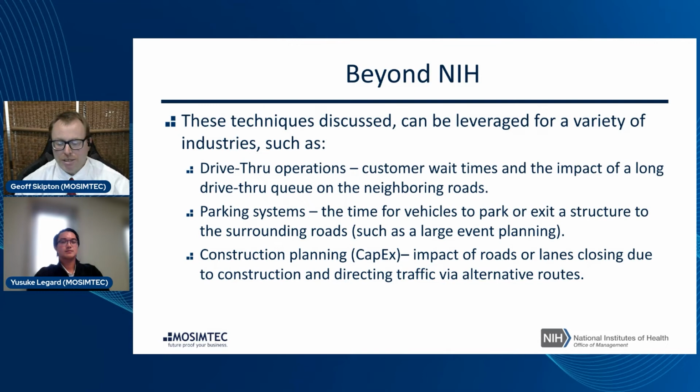I do want to note that we've used the road traffic library out of the box, and it's wonderful, but we use the stop lines, and then I particularly just manipulate the car. So when a car goes across the stop line, I can see where they're at, and I can see if they're at a window, for example, to get food or to make a payment, or if it's outside service, they're next to somebody that's trying to take an order. And then we just trick the car by setting its preferred speed to 0. It stops the car and then throws us a nice event that says, hey, I'm stopped, I need service. Once the service is complete, we can just set the car's preferred speed back to 5 miles per hour or whatever it happens to be, and the car can move on.